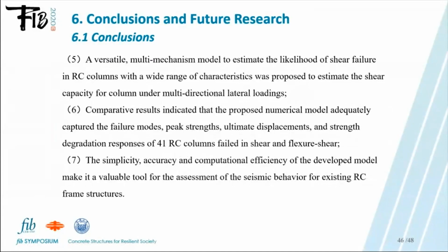A versatile multi-mechanisms model to estimate the likelihood of shear failure in RC columns with a wide range of characteristics was proposed to estimate the shear capacity for columns under multi-directional lateral loadings.